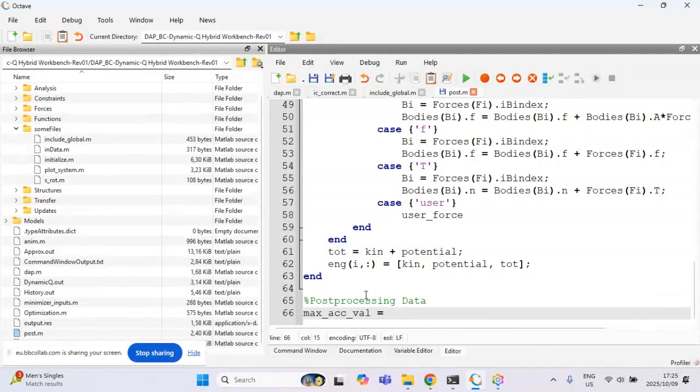to indicate I'm working with a maximum acceleration value. Now, if I calculate the acceleration magnitude, that will be, according to Pythagoras, just the square root of ax squared plus ay squared. So I can just say, well, let's use the square root, and you'll remember that from our post-processor, the accelerations vector that we get is RDD.